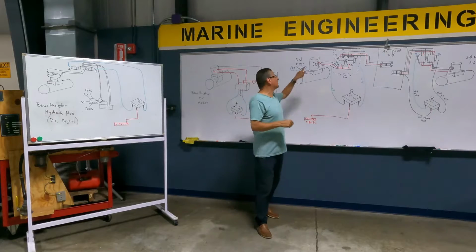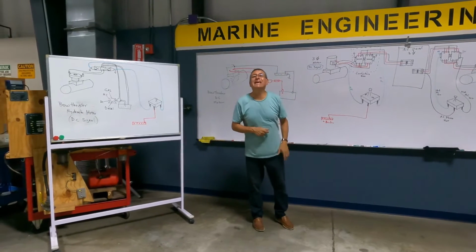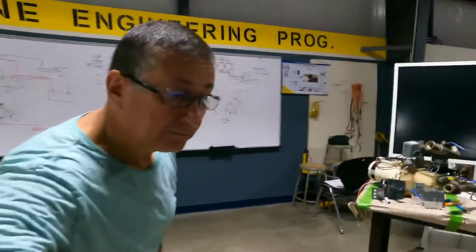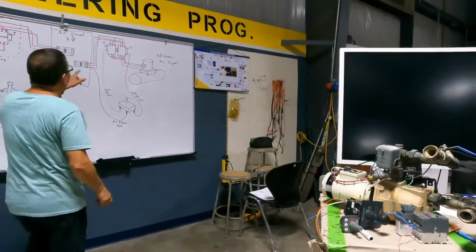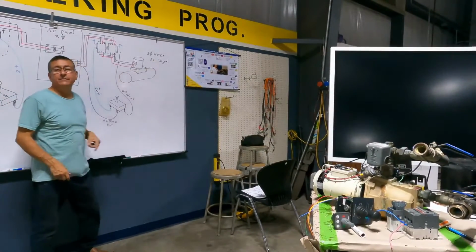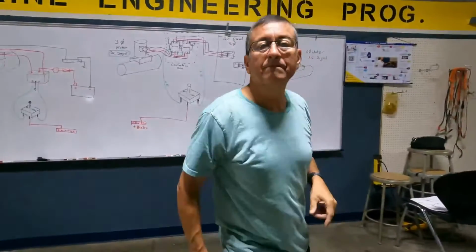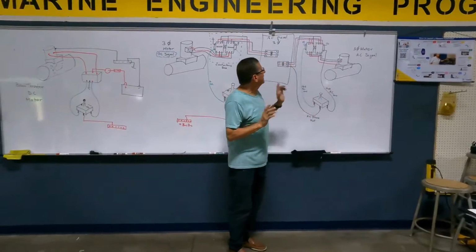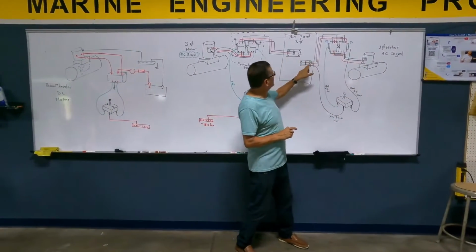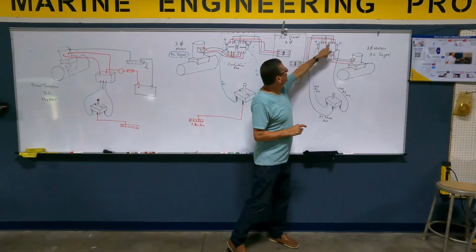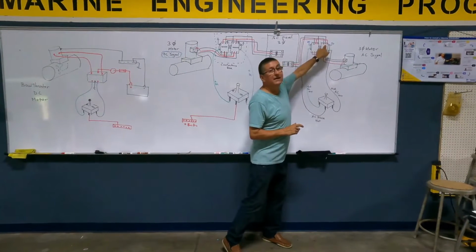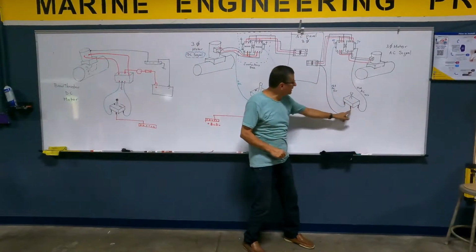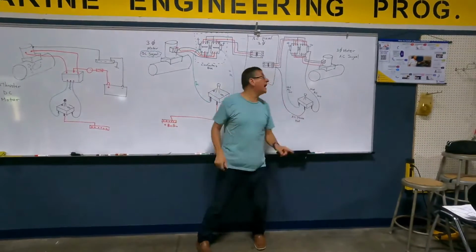Now we are going to activate the same 3-phase motor with an AC signal. Follow me, guys. The activation of this motor with an AC signal is practically the same. I have the same configuration from the breaker, phase 1, phase 2, phase 3. In the second one, I switch 2 with 3, and in the bottom, exactly the same connection, but the signal on the joystick in the middle is not a positive, it's a hot.